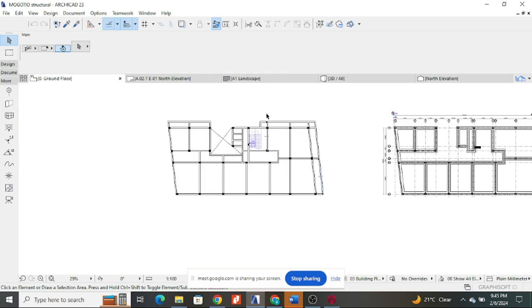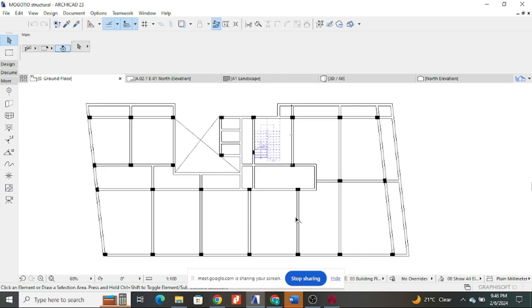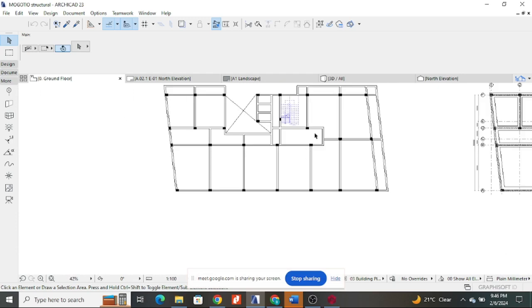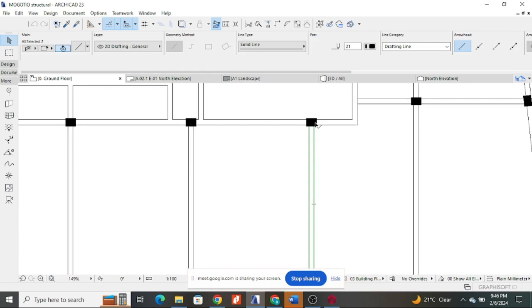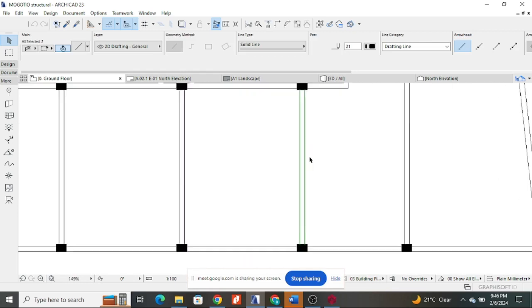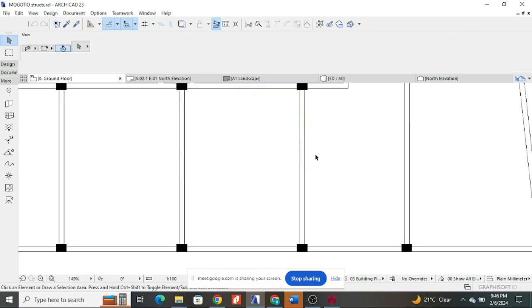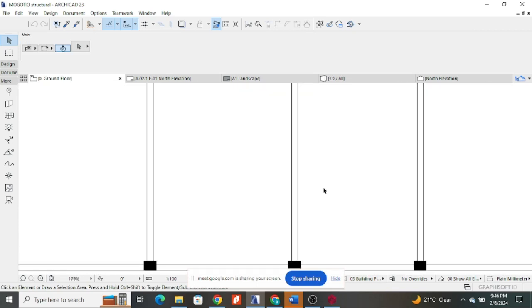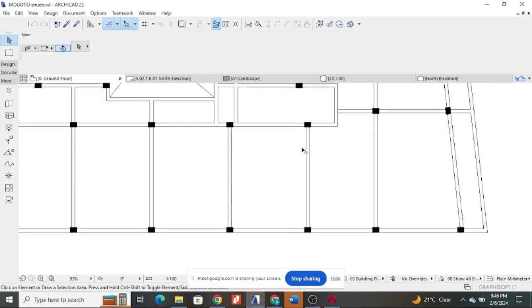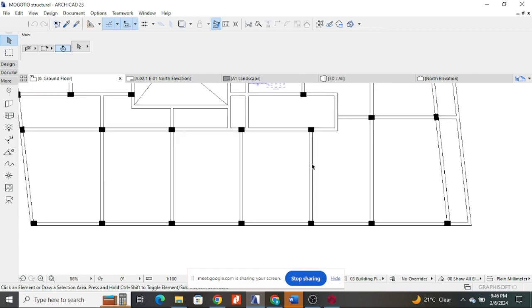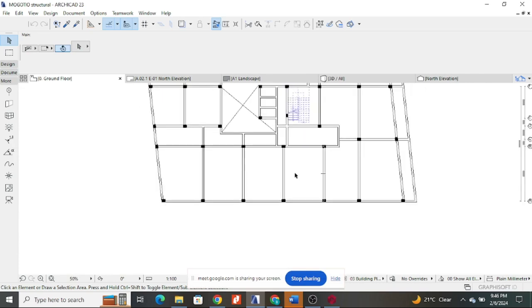Okay. So once I have preliminary designed, this is not design. I am preparing to design. What I'm doing is generating layouts. There are instances where I will generate such layouts, and then when I'm designing this beam, I realize that it needs a lot of reinforcement, so I will increase its size. I will maybe make it 600 deep by 400 wide millimeters. So that will be at the design stage. For now, I'm just doing my preliminary preparations.